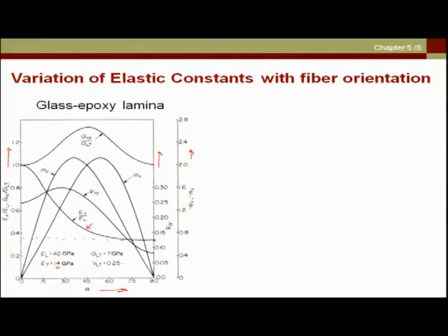So, this is one important observation, that for glass epoxy, Ex continuously decreases, and it achieves a minimum, and the minimum value is the same as that of Et.